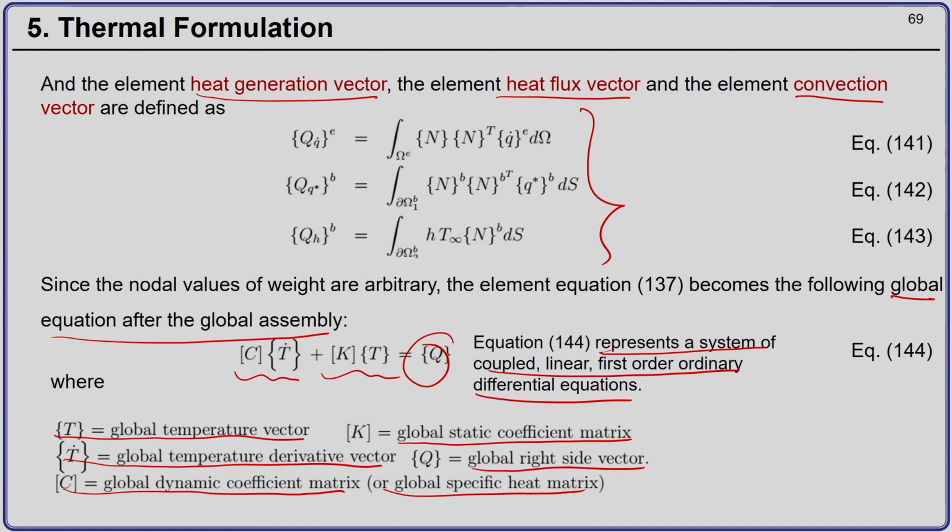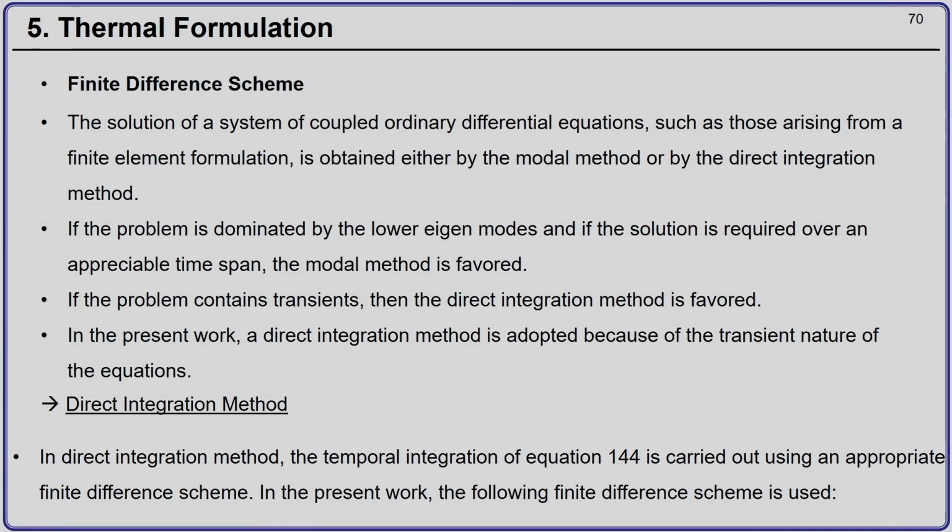Now, this is a first order linear ordinary differential equation, and to solve it we have to discretize the time derivative of temperature. For this we can again use the finite difference scheme, and here we use what is called the direct integration method.